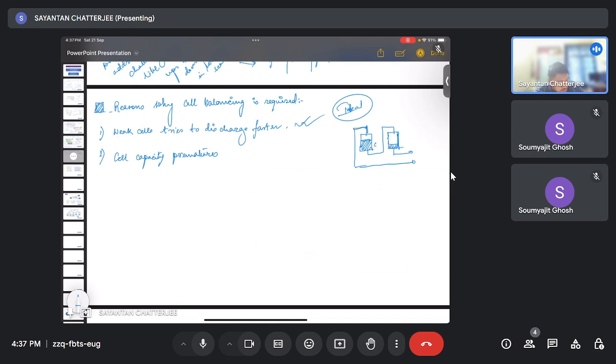so this much is the charge here, this is the charge here. So if both the cells which are connected in series here are fed to feed some, let's say, load, the problem that we can observe is that it will be a disaster, okay? Because one cell would be completely drained, whereas the other is completely on.